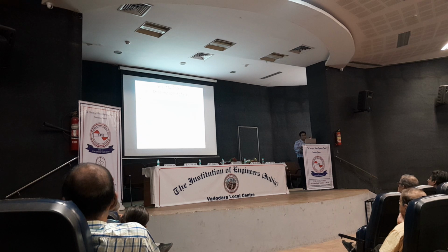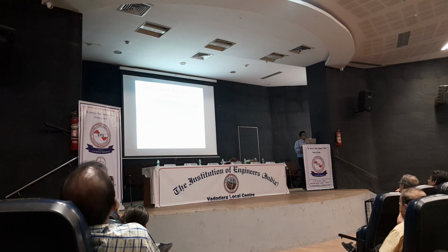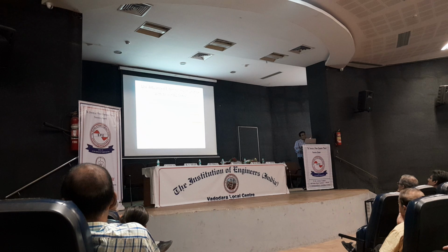Here field bus is selected, so you can select the number of buses. You can select the various zones, various areas, various screen layers in this particular dialog, and you can get the particular information with this PowerWorld simulator. You have the advanced filtering options also to select the various information.